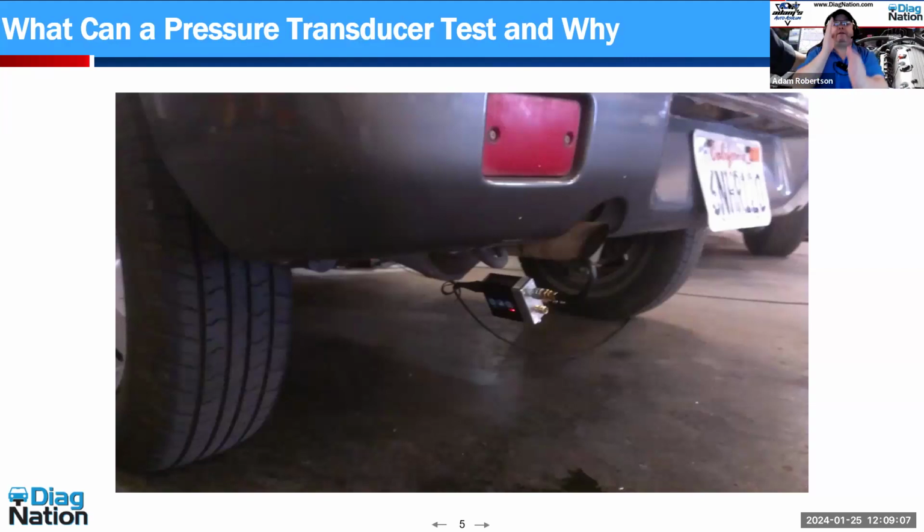So 1 3 4 2, 1 3 4 2, 1 3 4 2, and in between is that little suction, if you will, of atmospheric pressure pushing back in. Now, some of us in the past, including myself, have worked for maybe one of the people that got us on our path to this, where they maybe hung a napkin or a dollar bill behind the tailpipe to watch the flutter of it, and they could tell you that if it sucked back into the exhaust, we had a misfire.